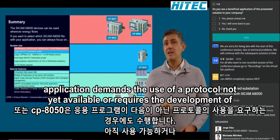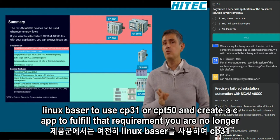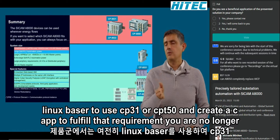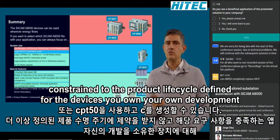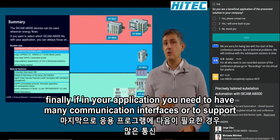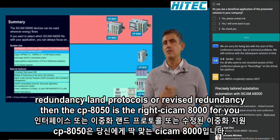Also, if your application demands the use of a protocol not yet available or requires the development of some algorithms or special functions not available in the SICAM A8000 family, you can still use the Linux-based RTU CP8031 or CP8050 and create a CAP to fulfill that requirement. You are no longer constrained to the product lifecycle defined for the devices. You own your own development. Finally, if in your application you need to have many communication interfaces or to support redundancy LAN protocols or device redundancy, then the CP8050 is the right SICAM A8000 for you.